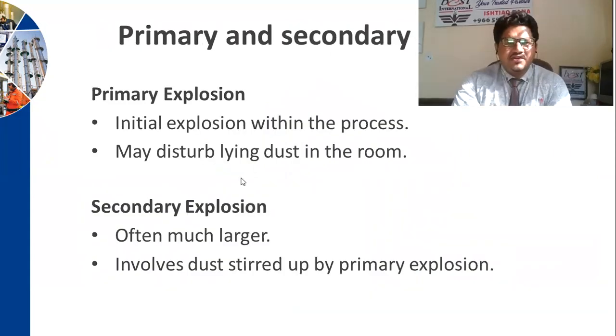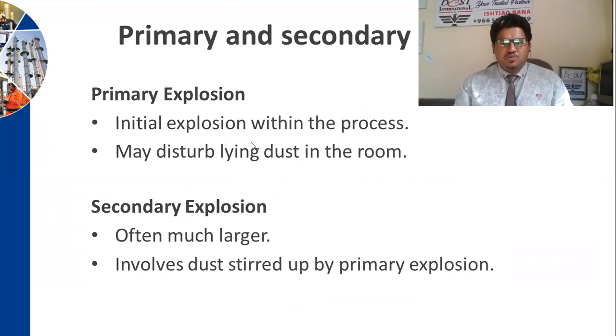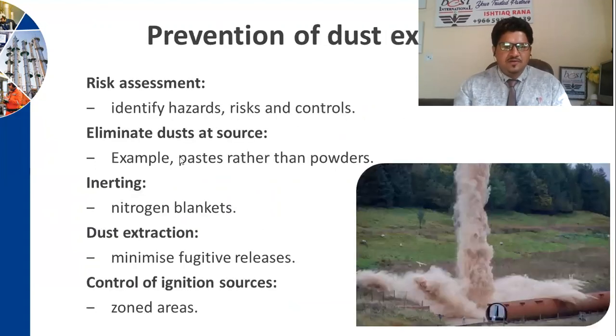The primary and secondary explosions. A primary explosion is the initial explosion within the process, which may disturb lying dust in the room. A secondary explosion is often much larger and involves dust stirred up by the primary explosion. So the secondary explosion involves the dust.